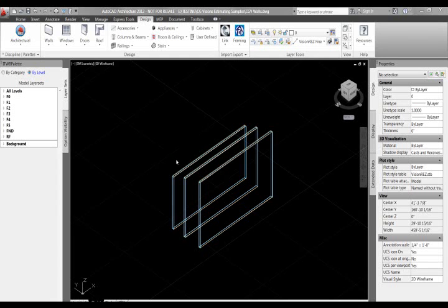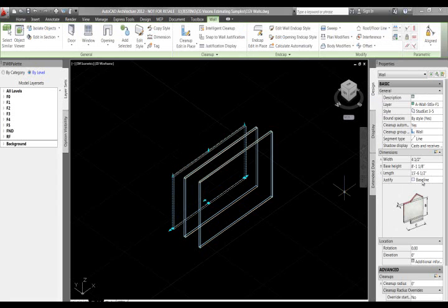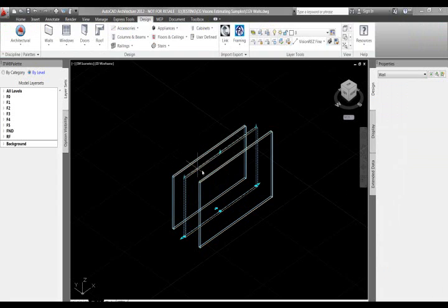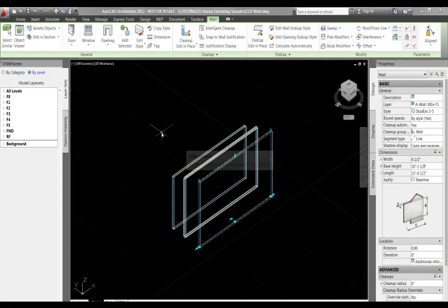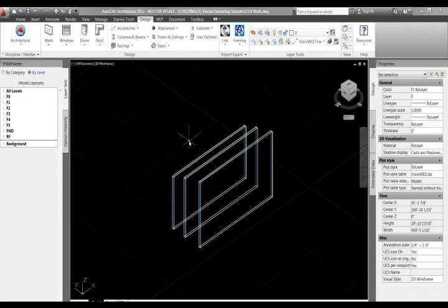This is a demonstration of how to set up a takeoff item in VisionREZ using walls. Here in AutoCAD I have 3 walls, same wall style. One wall is 8 foot 1 1/8, 9 foot 1 1/8, and then 10 foot 1 1/8. I'm going to export these and set up the bill of materials to take these off.